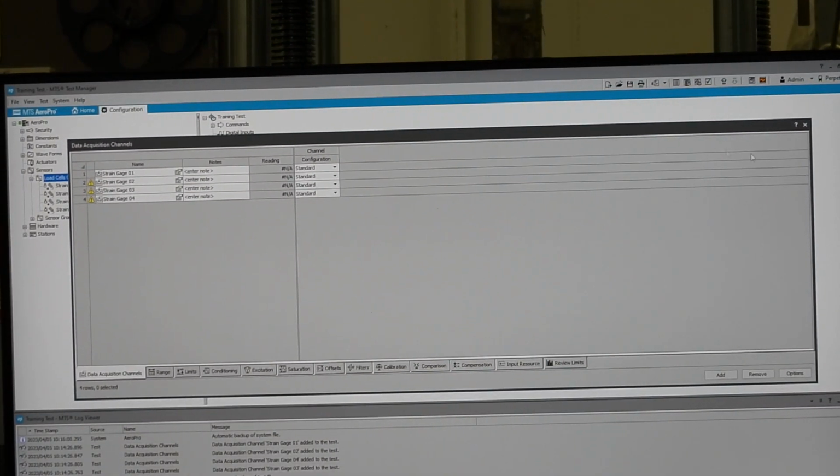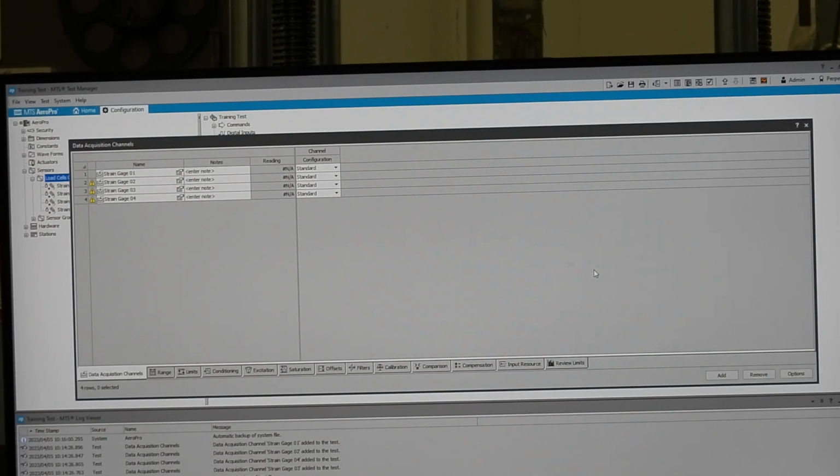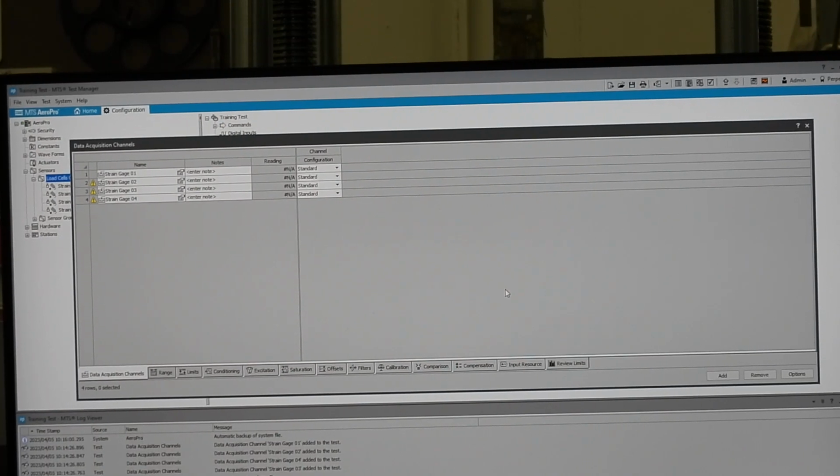This will read thermocouples? Not natively, no. This would be if you conditioned a thermocouple externally as a voltage input. An amplifier before it goes in there? Yeah, right. I think we do support some other equipment. I think it's the popular ones, the VTI 1629, I think is the thermocouple input.